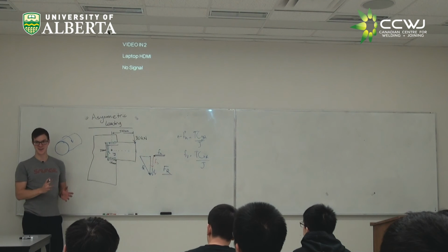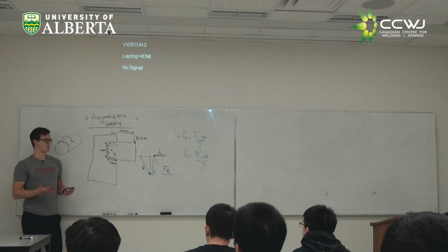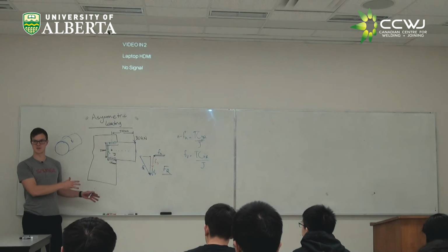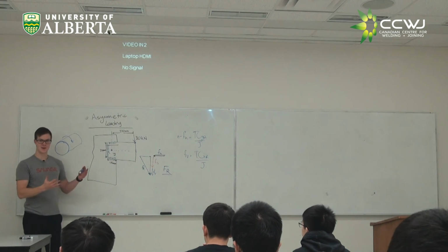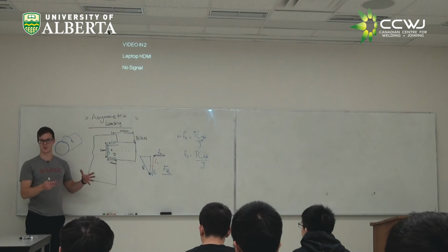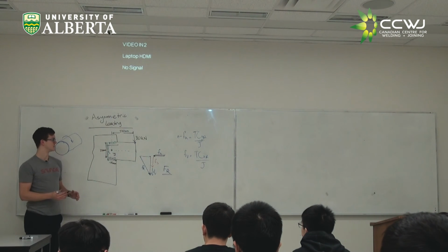Now, in theory, more conservative would be to say we won't go up to 1.5, and we'll knock everything down to 0.85 to make sure we're always going to be safe. Why they don't do that, I don't know. I'm not a master of the American codes. They don't actually worry about some of that stuff in their structural codes the same way the Canadian codes developed. These are all still a little bit of guidelines, and there's some conservatism worked in, so the different codes have different ways of working in their safety factors and their kind of buffer.